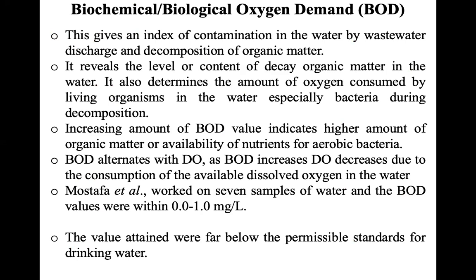Now, we say the BOD, or the biological oxygen demand, or the biochemical oxygen demand, gives an indication of contamination in the water, especially by waste discharge and decomposition of organic matter. We are saying an increasing amount of BOD indicates that a higher amount of organic matter is present, and so it's not easy to treat such water bodies.